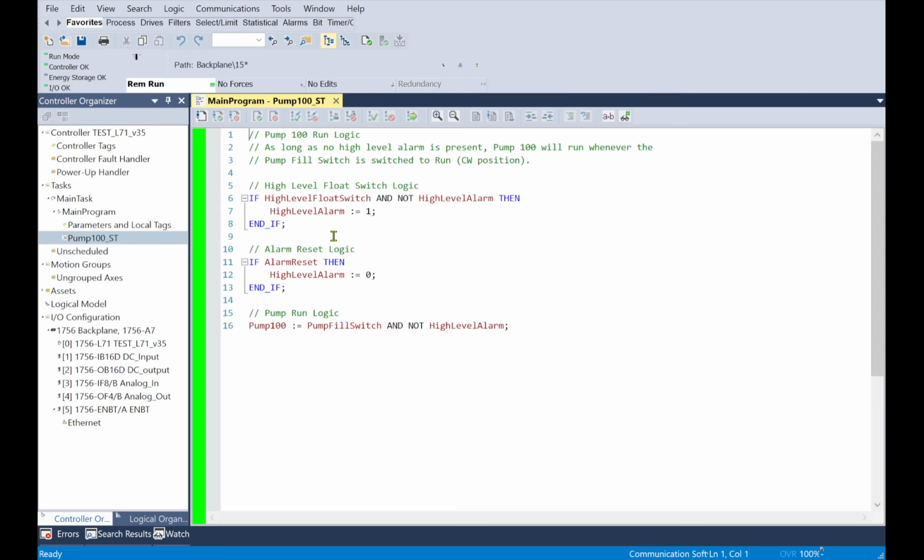the equivalent of those permissive trees. But you have to realize that that's a translation. So the little scenario I just had, where that logic itself is kind of flawed depending on the scan cycle, if you catch that, that HMI would probably not factor that in, and it would give misleading results. There's nothing like looking at the real logic to figure some of these things out.